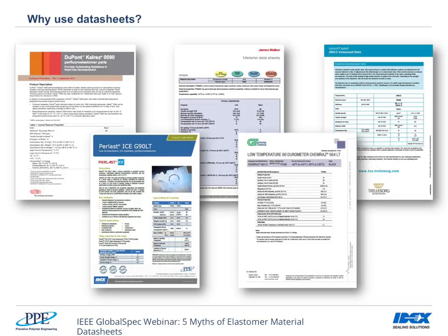You'll find information of where the material may be good at, which particular applications, which particular products. Effectively, the text will sing the praise of the material. When looking at numbers on the datasheet, as I've mentioned, they are often quite generic. For example, if you look at the hardness for a material, more often than not it will be a 90 Shore, a 70 Shore, maybe a 75 Shore, maybe even 80. But you'd never see an 82.3 or an 85.6.